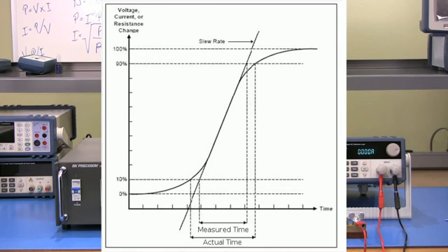The indicated measure time will be used to calculate the slew rate. Hence, the slew rate calculation is simply the difference in the load change, in this case rated max current minus 0 amp, all over T, where T is the measured time from 10% to 90% region, and rated max current is the specified maximum current of the load under test.